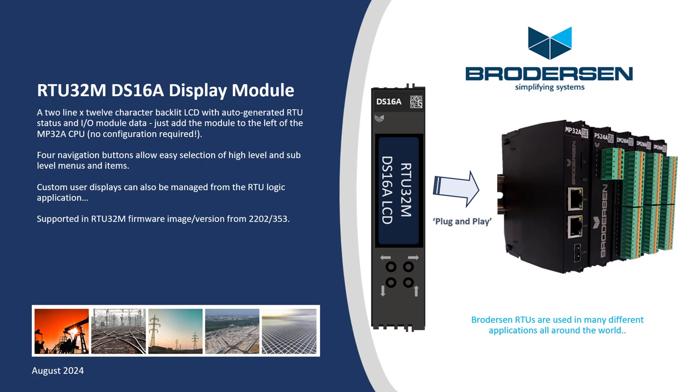Simply plug it into the left side of your RTU, and if you've got the current firmware and an application running in your RTU, the firmware will manage the display contents for you. There's 2 buttons, left and right, that allow you to select which module you'd like information about, and then there's up and down buttons that allow you to scroll around through the channels or the information display.